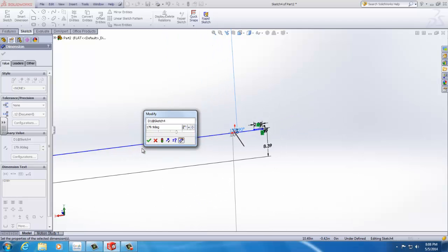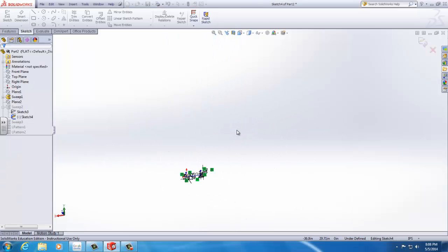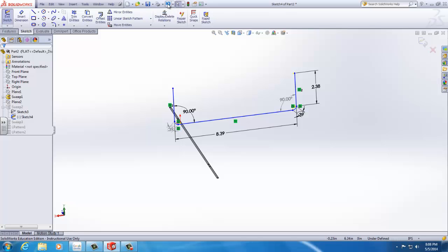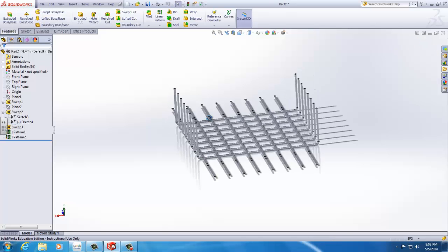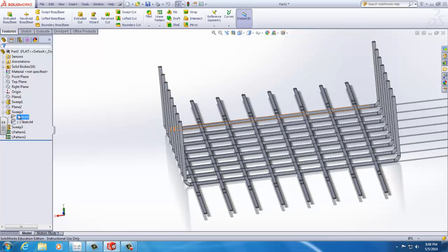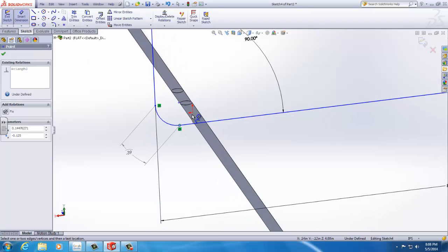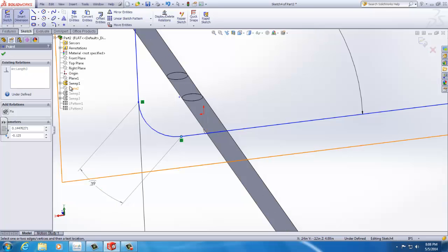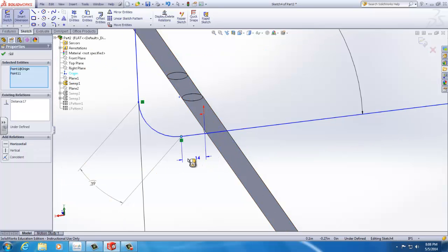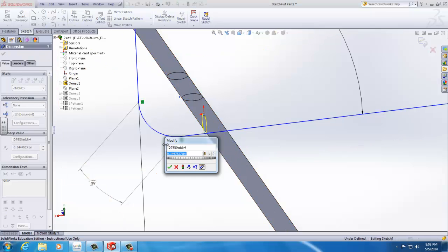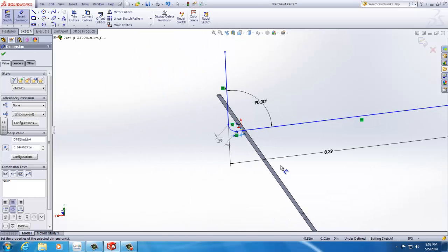So it did give it a thickness, but the sketch wasn't strongly defined. The problem is if it thickens itself over itself, it won't work. So if you go too thick, sometimes it just doesn't work. But I think we can adjust it now. Sometimes you have to fix it up a little bit to make it work. I think it's overlapping here. That's the issue.